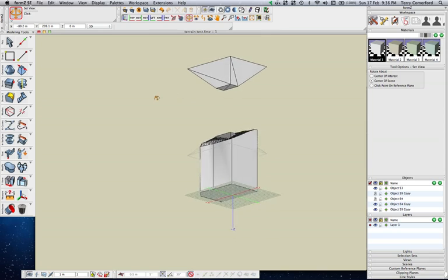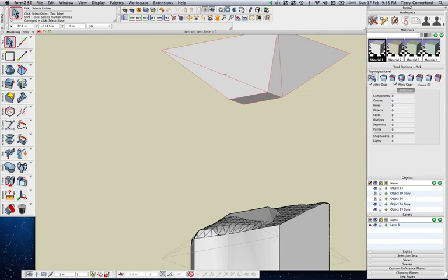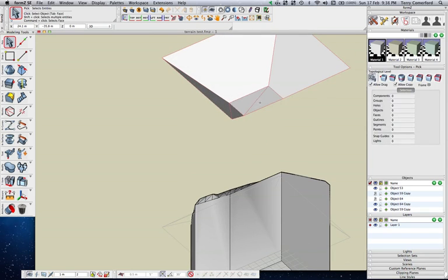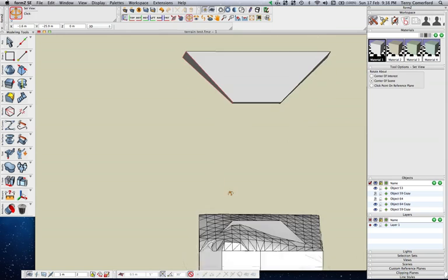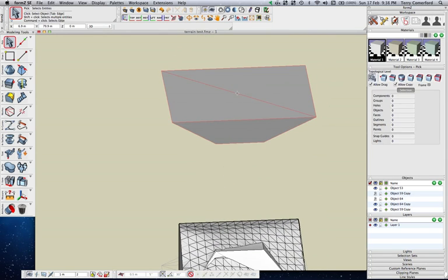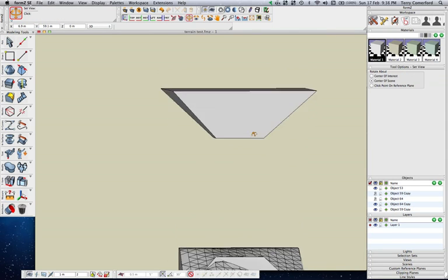So I go to pick tool. I might try and tidy up these faceted faces here on this surface. That should be a plane of face there. So I'll hover over that line, press my tab key until I select just the line and delete it. Just to tidy up that. I feel it'll be a bit tidier geometry if I do delete these. Okay, tab that one. Oops. Hover over, tab that one. Hover over that one, tab that one. Okay, so that's tidied it up, and maybe even the top surface also, and tab that.